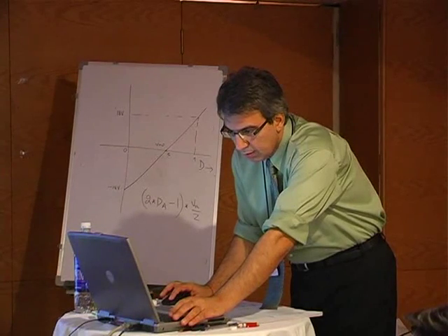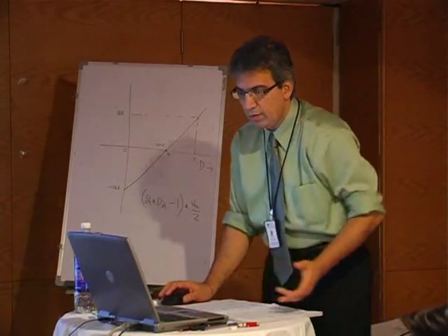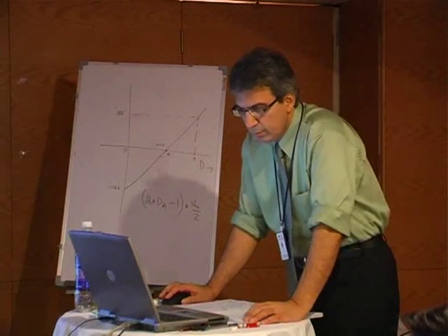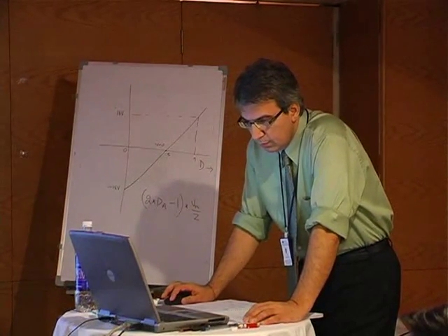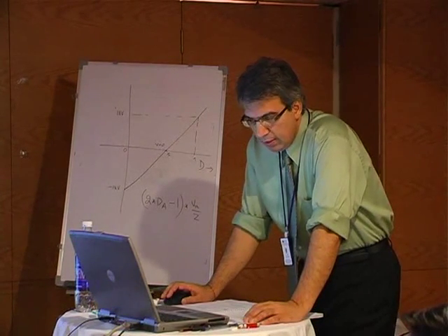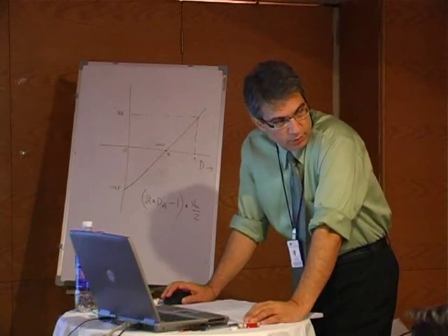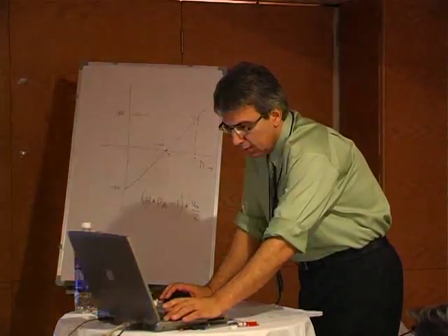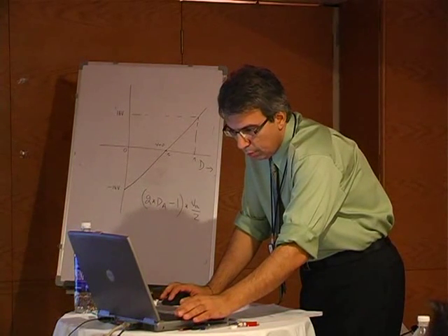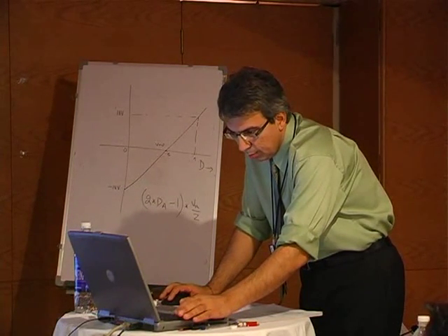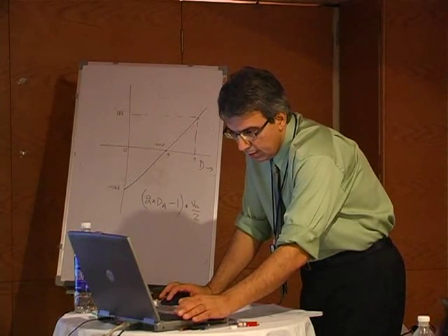Switching frequency is 20.5 times 47.62, which is about 976.21 hertz, right? And so you have harmonics. 976 is somewhere in the middle, but the middle harmonic is missing, and you have the side bands here. And here also you have the side bands.